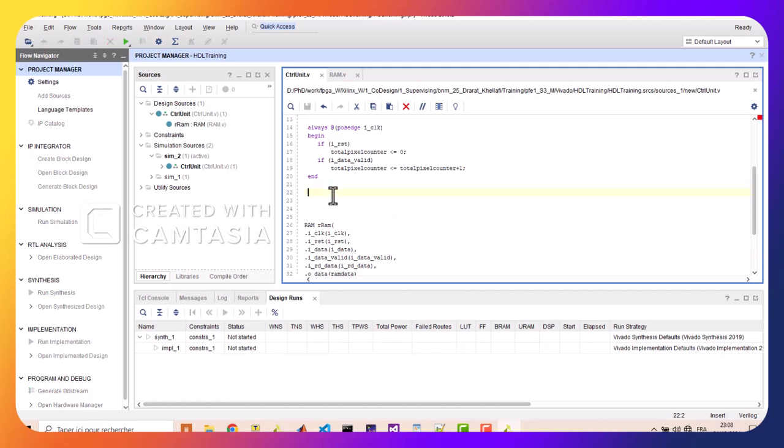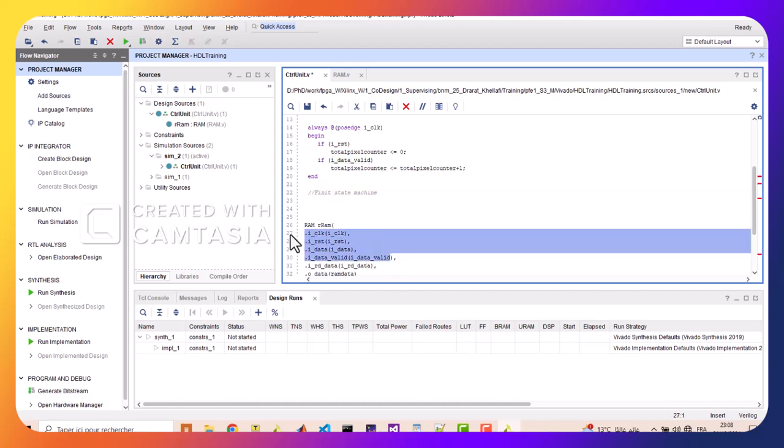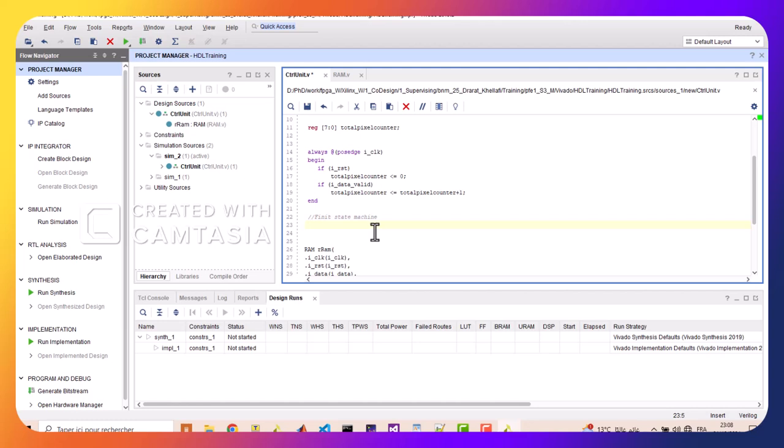Now we need to set up a state machine. That will give us the possibility to switch from this writing to reading. So this will become equal to 1. Same thing, we need a process. When we say synchronous, it means it needs the positive edge of our clock. Again, and